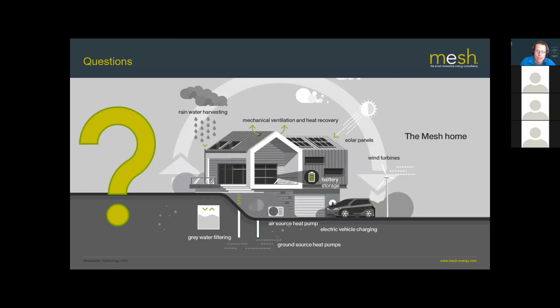Patrick's asked about east-west splits to make best use of sunlight, typical peak demand times, morning and evening. This is also the due south optimal azimuth you mentioned. Can you explain the logic and pros and cons of this, please? Okay, so east-west splits. If you have a flat roof and you put an east-west split, and unfortunately I don't have a good photo of this, but what you can do is you effectively create a sort of little ridged roof upon a roof with your panels, with half facing east and half facing west.